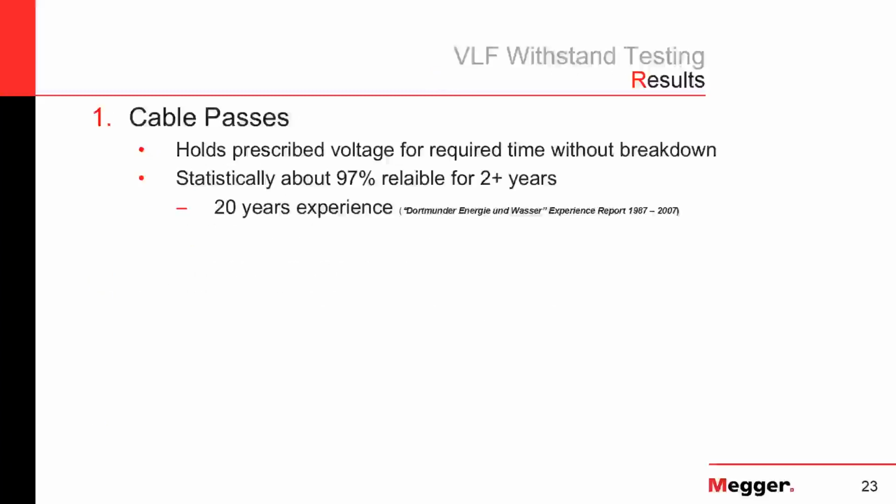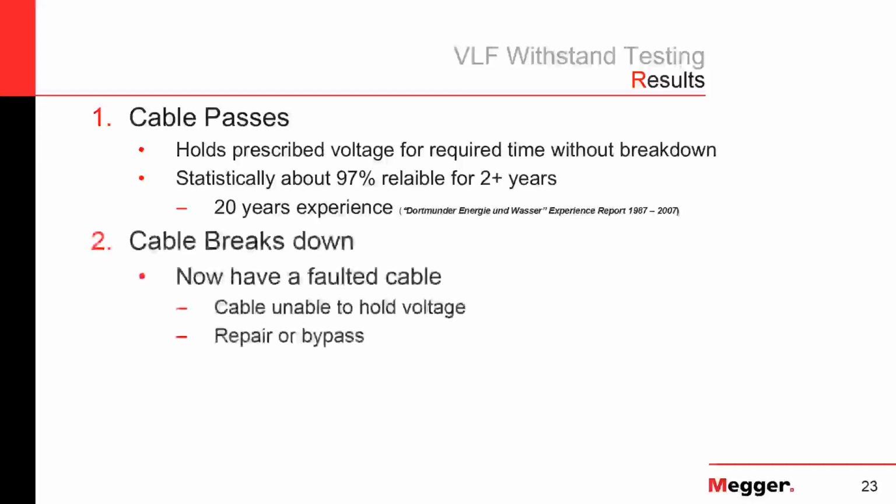So the results then: the cable can pass the test. In that case, it's held the prescribed voltage for the required time, and it has not broken down. Statistically, we find that that's about 97% reliable for the next 2 or more years. That's based on field results.